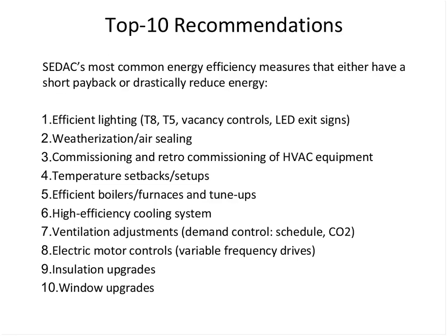Then we look at the weatherization and sealing of the building. We look at a large building, probably commissioning or retro-commissioning or recommissioning of the building HVAC. We're finding anywhere from 15 to 30 or 40% energy savings in newer buildings. These are buildings that are 5, 6 years old that have a building automation system that is not operating properly. Great energy savings from them.